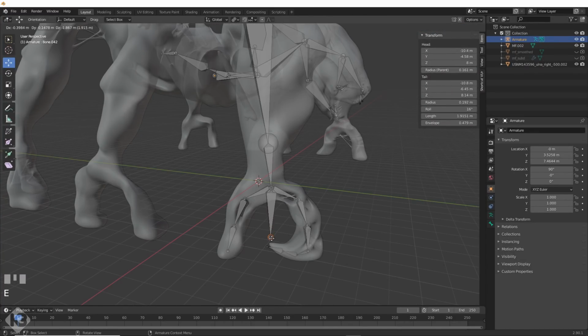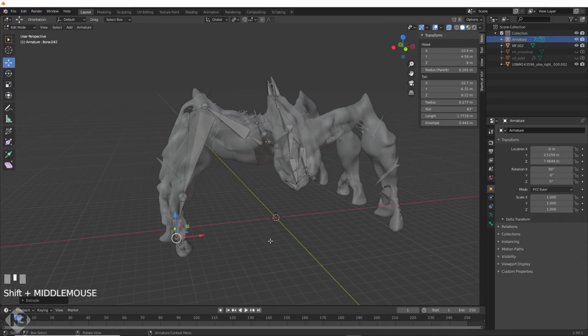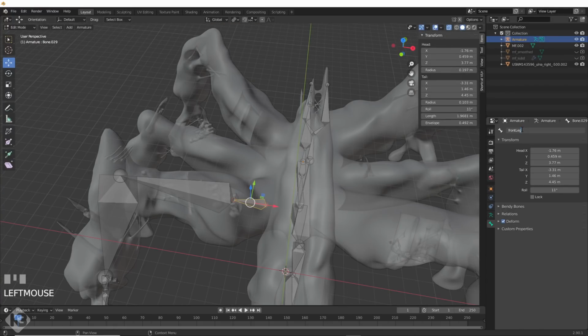Then here, I drew one bone that will be the controller bone. I'll use this later to move the legs. Now I rename the bones. Front leg.r. The .r is important as we will symmetrize this later, and the R's will change to L's for the left side.